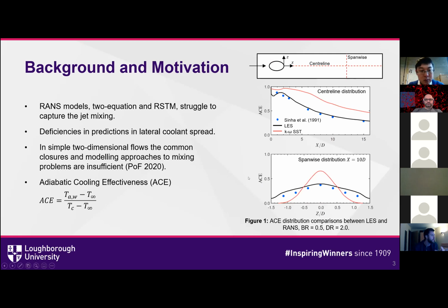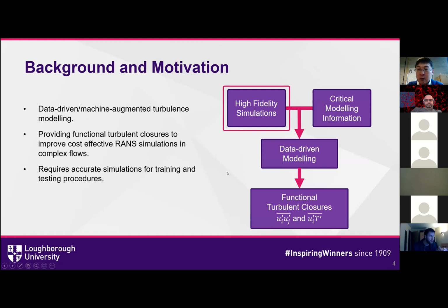So this inspired us to look into a simple two-dimensional flow, looking at common closure models in a simple two-dimensional separated heat transfer case, where we saw that there were lots of insufficiencies in these turbulent closure models. And that has inspired us to move on with data-driven and machine-augmented turbulence modeling approaches, where our essential aim is to output functional turbulent closures that better describe this mixing behavior in this range of flows so that they can be used in industrial cases.